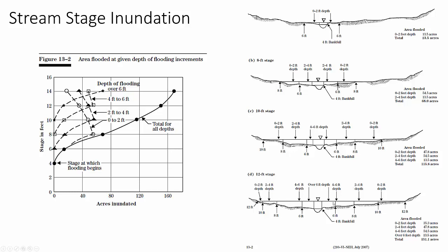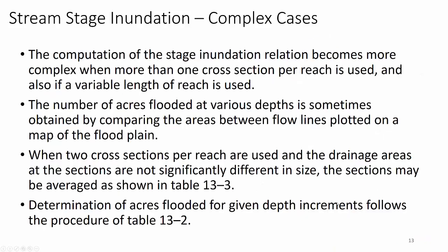Now, this becomes important because of the tractive force of that water based upon its weight, its depth, and that tractive force is erosive depending on the velocity, and that will cause erosion and damage, as well as also the damage to structures and other items of concern within the watershed.